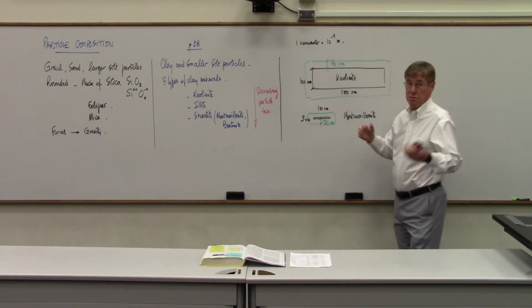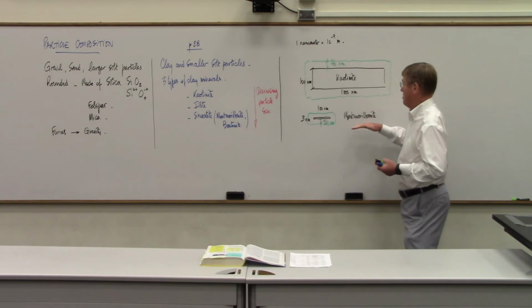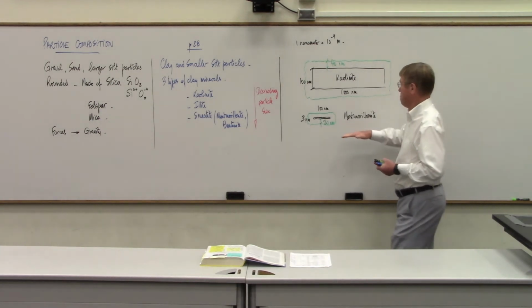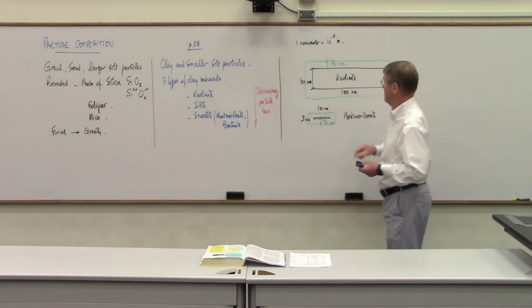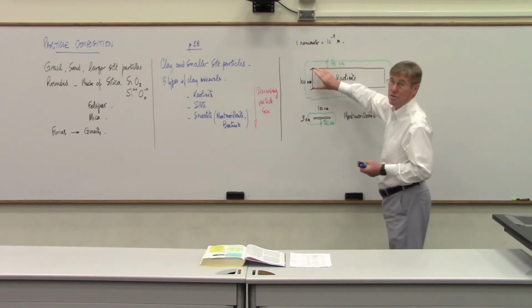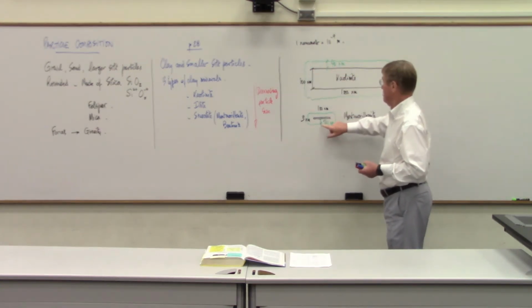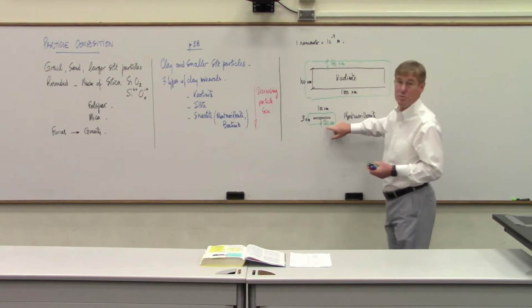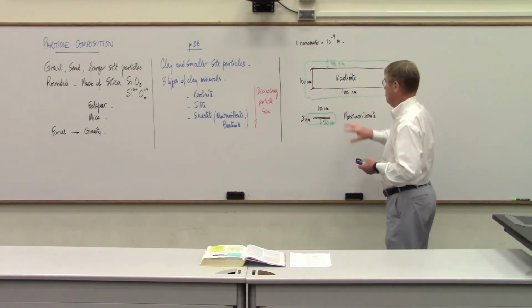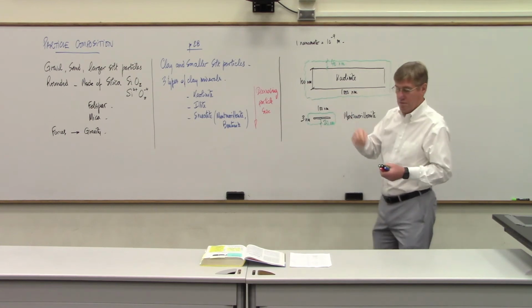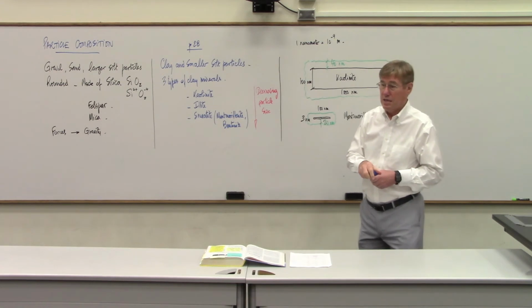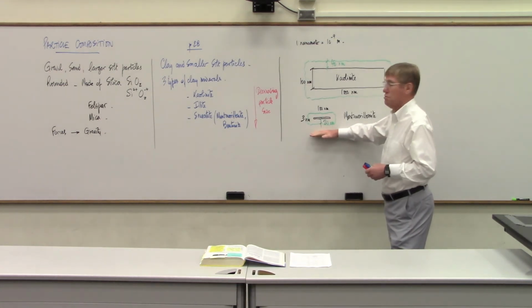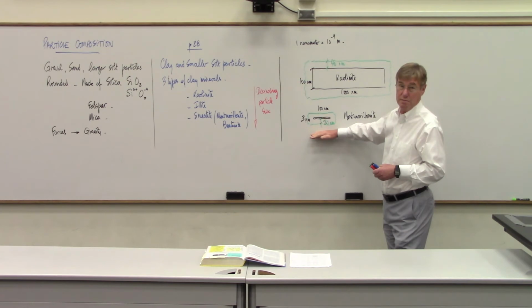So you say, who cares? Well, we do care for one reason, because you see this adsorbed water here is 20 to 3. Its adsorbed water is 40 to 100, so that's 40%. This one is, what is this, 600% or so, more. So if you do the analysis and you find out that you have a lot of Montmorillonite, then this material has a tremendous ability to swell.